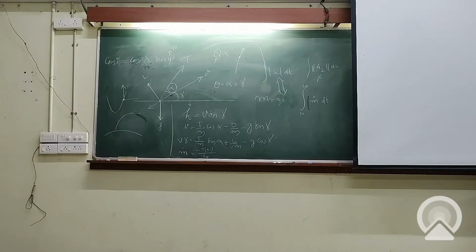Their constraints are also different. Capsule, say the control we have, there are no aerodynamic surfaces. It is not a flying wheel. It is a stone. So what are the controls that we have? Bank control. We can modulate the lift and somehow meet the targets to some extent. Then we have shuttle-like space planes, which are no less than an aircraft, where you have all kinds of aerodynamic surfaces which you can modulate, you can fly, but unpowered. Then this re-entering spent stage is a very interesting problem.